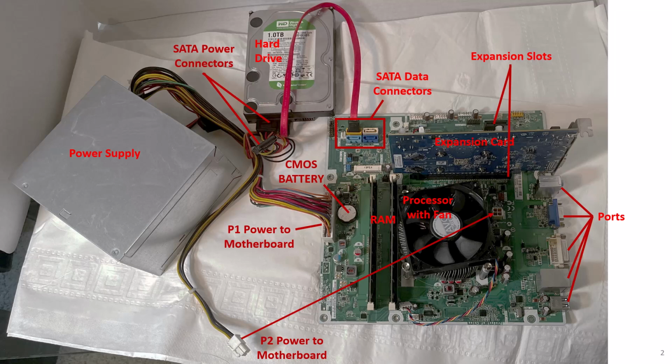As you can see, the power supply has a larger 24-pin ATX power connector labeled as P1 power and a smaller 4-pin power connector labeled as P2 power. This motherboard has 4 SATA data connectors with one connected to a hard drive. There's one SATA power connector connected to the drive with additional power connectors available for a second hard drive.